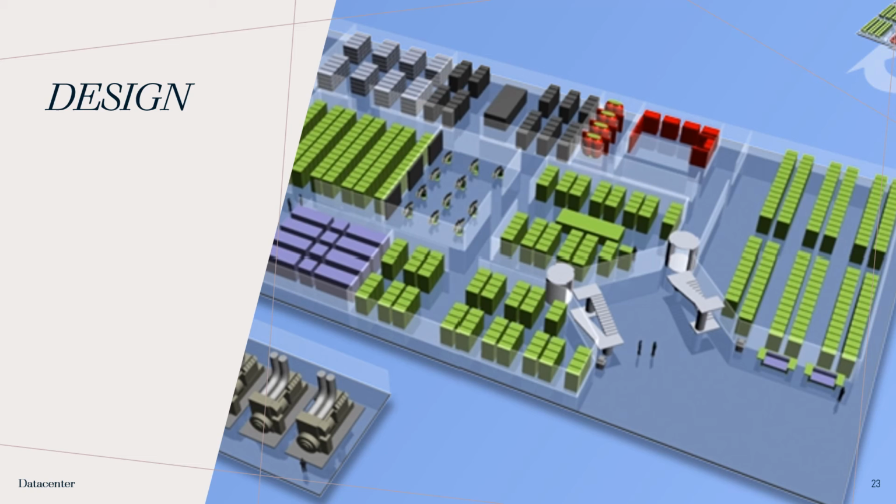Design. When we have identified one or more potential locations, it is important to draft a design for the building. Having a full understanding of client requirements allows designs to be created that fit the site and the surrounding area. It's more than just the number of racks and amount of power. Resilience, floor load, efficiency, renewable power, and local restrictions are just a few of the important items to consider before proceeding with any planning applications. In parallel to the planning applications, work can proceed on identifying our construction partner, reviewing and updating our budget, and creating a construction and fit-out project plan.